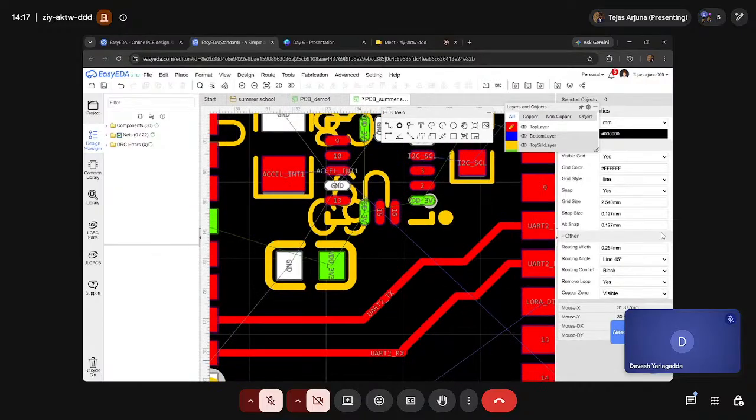Why does that happen? In PCB design or anywhere in electronics, a signal always moves through the path that has the least impedance, if it is not DC. You should have heard about impedance in AC, right? In this high frequency state, the capacitor's impedance is low, because it is 1 by omega C. So omega is high, and the total impedance of the capacitance will be low.